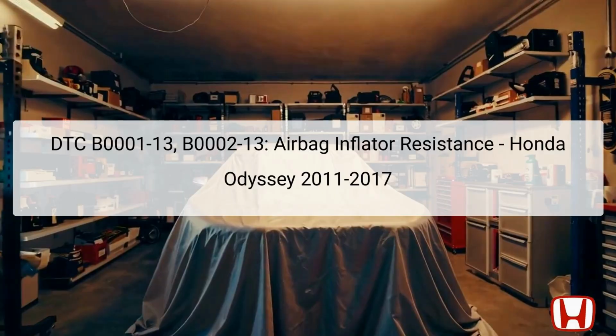The Diagnostic Trouble Codes, DTC B0001-13 and B0002-13 indicate an issue with the driver's airbag inflators in the Honda Odyssey 2011 to 2017 model years. Specifically, B0001-13 implies an open circuit or increased resistance in the first inflator, while B0002-13 pertains to the second inflator.